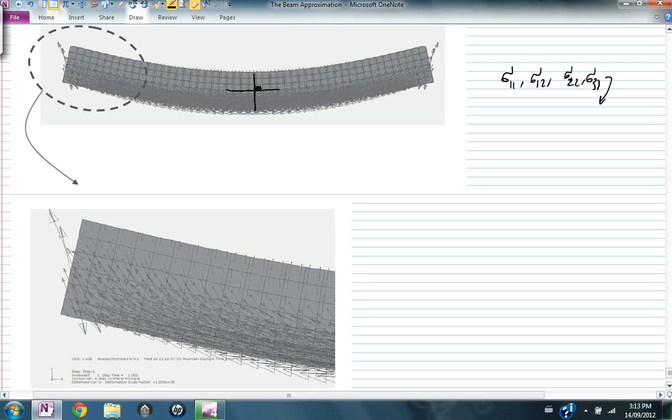And in these cases, you can draw, for example, using finite element analysis, as you see here, a map that shows you the direction of the principal stresses at every point. So, for example, closer to the support, you'll find that the stresses are higher in this direction. Closer to the middle of the beam, the principal stresses have this direction. And so based on this analysis, if you're using concrete, for example, you'll be able to align your steel bars according to the direction of the principal stresses. You'll find for this particular simple beam, you don't have any tensile stresses at the top, so you would minimize the number of steel bars that you use in the top.